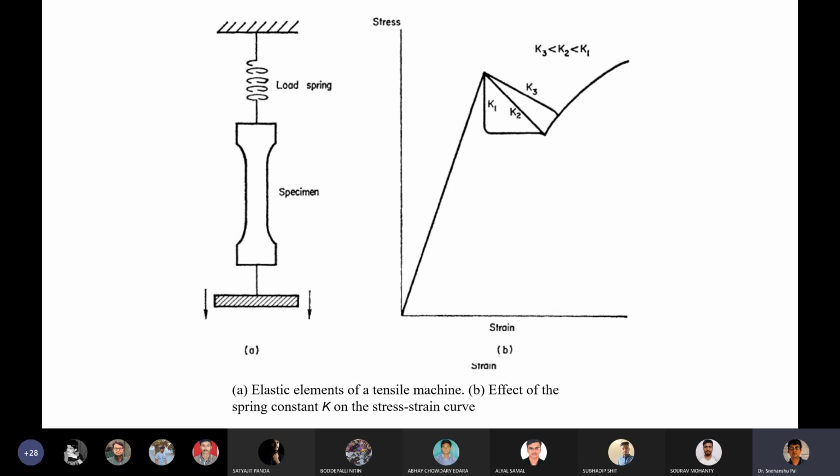So here you can say that the stress barely falls below the nucleation stress, so the Luder bands will be forced through the specimen at much higher velocity, and that actually shows the effect of axial loading on the magnitude of yield drop.